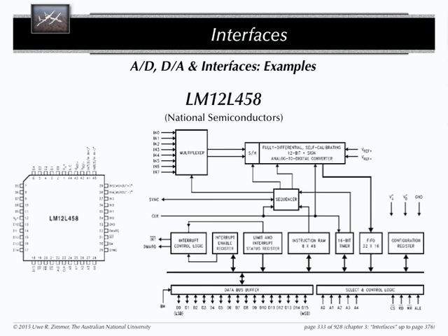You nailed this to a certain address in memory. What you usually do is you define all of your registers for this device, and then you define one large block which has one large record, which has all these registers in one record, exactly in the sequence as they appear in your device. And then the only thing you do in the higher-level programming language is you nail the base address of your device to the beginning of this large record, which contains all registers of my device.